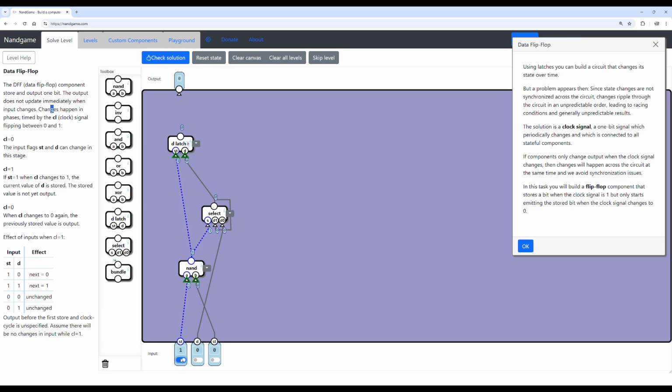So right now, nothing's happening yet. Even if we want to set D to 1 and we enable writing, because we need to pulse the clock. So boom, clock pulse, now it's 1. And now we're going to make it read only. So no matter how much the clock pulses, you can see this NAND gate is kind of controlling that and blocking it.